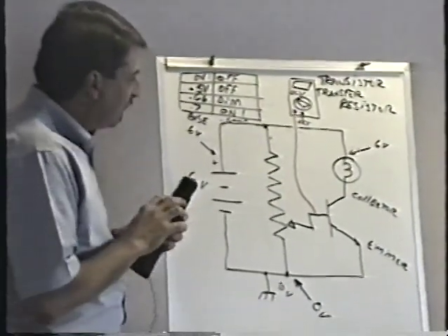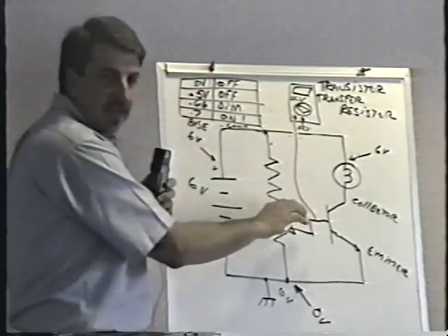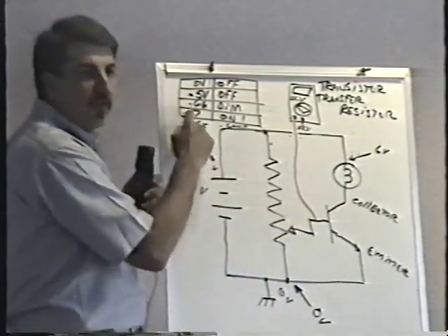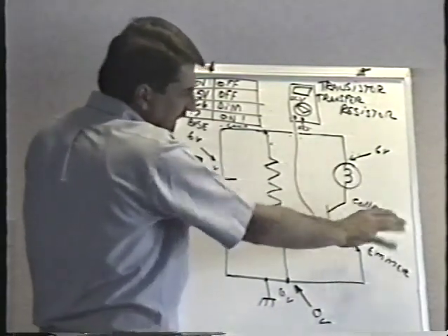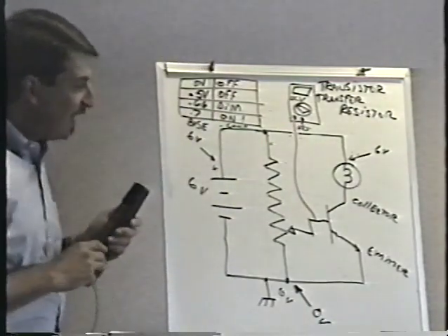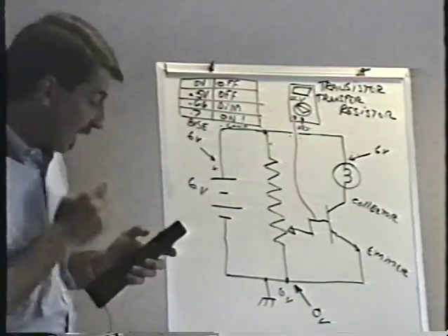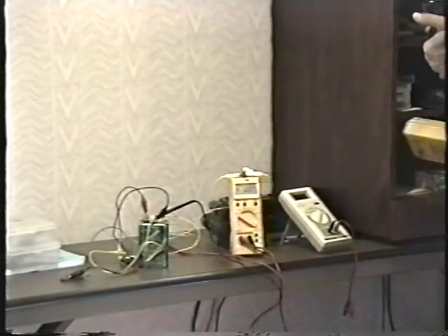All they're talking about is that an itty-bitty tiny change on the base, in this case just this 0.04 of a volt, can make the difference between something being, let's say, just partially on and completely on. Now, if we add another meter to this thing, we can get a real good idea of how this thing works. I'm going to add another meter here.